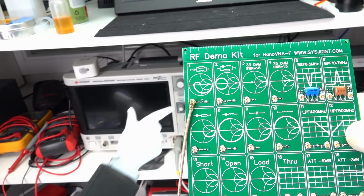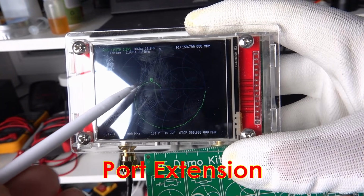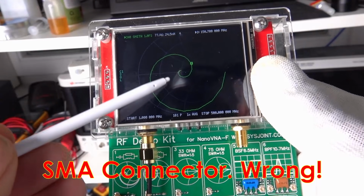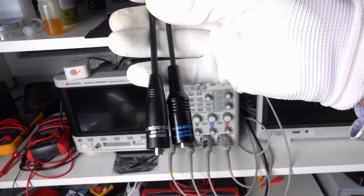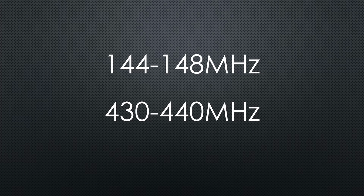Here are the results. With calibration on the board as well as with the port extension, the measurements are very similar. The result with the calibration plane at the SMA connector of the VNA is very different and wrong. With all this knowledge, we can answer our question from the beginning. Which antenna is better? They look very similar. Same manufacturer and same type. They should work on 144 to 148 and on 430 to 440 MHz.